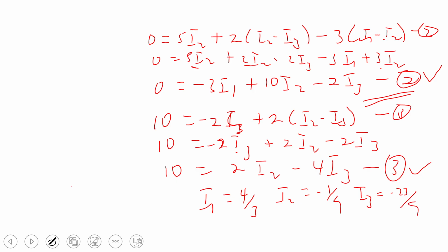So if you solve the other way, either one of them will be positive or negative, right? So try that yourself and realize we are all going to get the magnitude to be the same. One will just be negative and one will be positive, to show that you can assign your current direction anyhow when you are solving circuits with Kirchhoff.